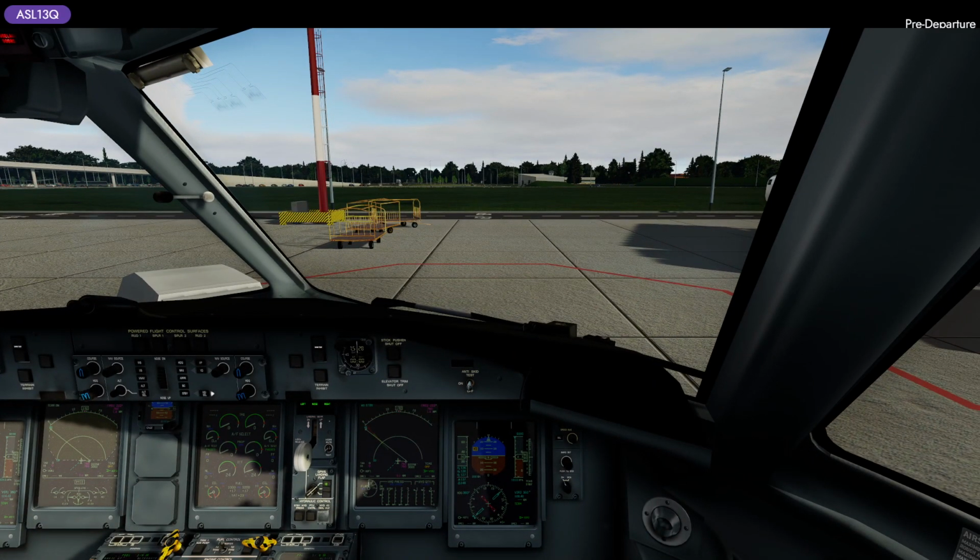What I like to do now is double check there are no special noise abatement procedures. So just the regular 1,000 feet above ground level. Let's see what it says for the noise abatement, noise departure, start and pushback. The noise abatement procedure says aircraft operators should follow NADP 1 noise abatement procedures according to the ICAO document. And I want to double check it just not to say something incorrectly.